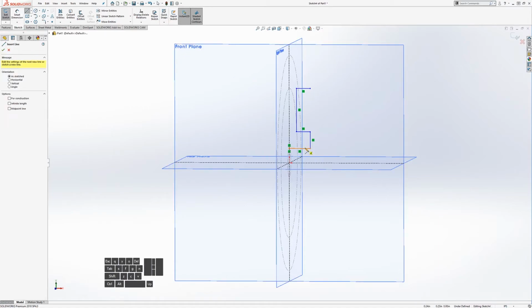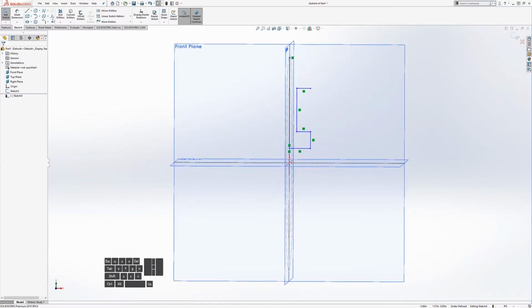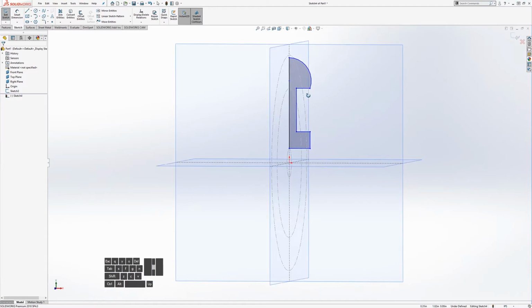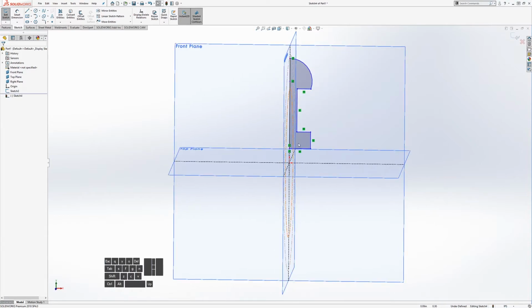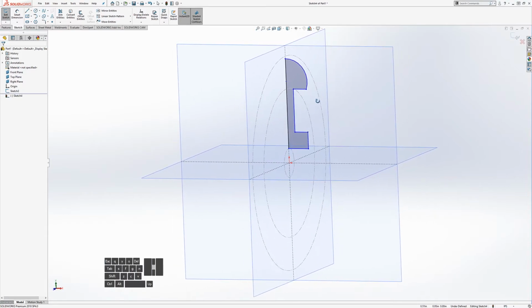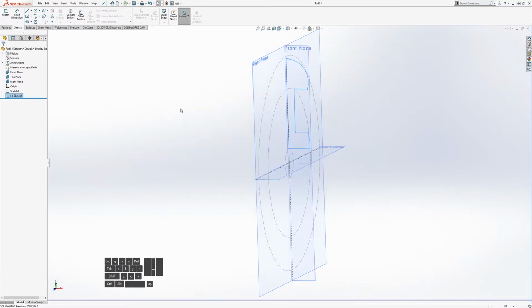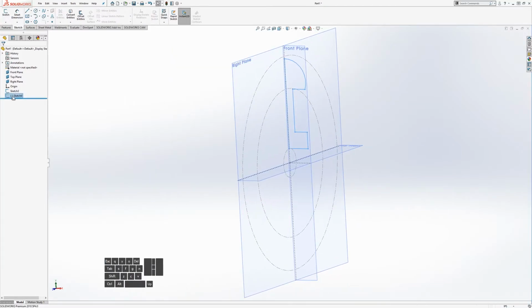So from the front, kind of looks like that, and then we can put the tire in there. So I'll create an arc, tangent arc, just like that. And you can see that that's shaded in now. So SolidWorks can tell this is ready to create a feature because it is a closed sketch. So we can get out of here, and you can see this minus symbol in here.